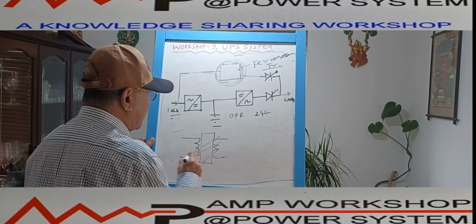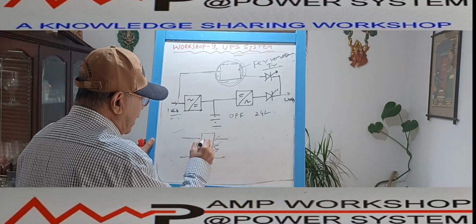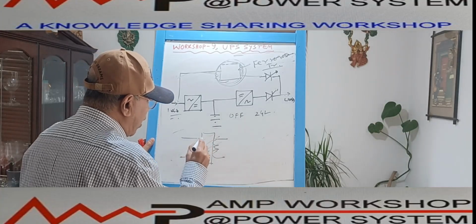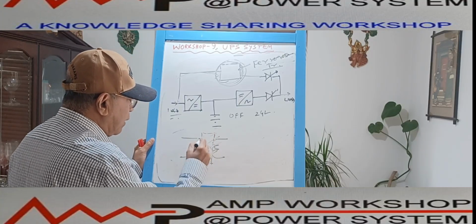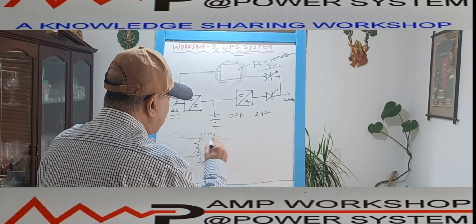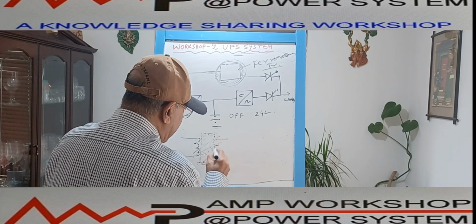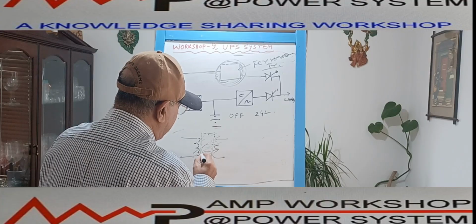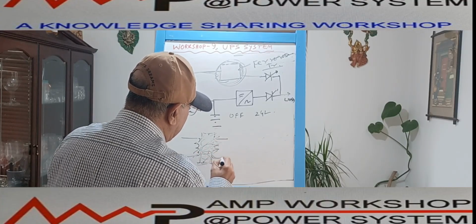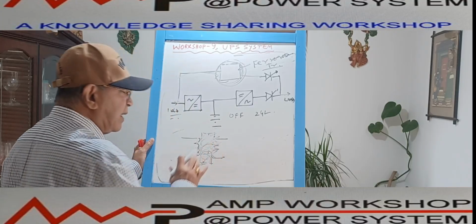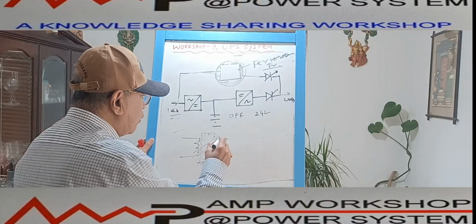How is the magnetic flux growing? This is a magnetic core, and the winding is wrapped on the core. The moment we give the power supply, the core is magnetized and produces a flux. That flux links at the secondary winding, which is also wound on that core. Then this flux is linked with the secondary, and if that flux changes, it will produce a voltage.